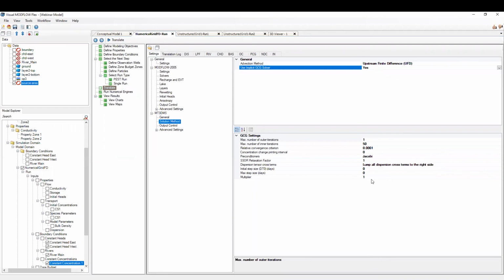And here we are just going to make one adjustment within this multiplier factor, which is related to the size of the time steps that's going to be used to do the transport calculations. And yes, let's change also the maximum step size to 200 days. And those should be okay. Let's actually save this again.